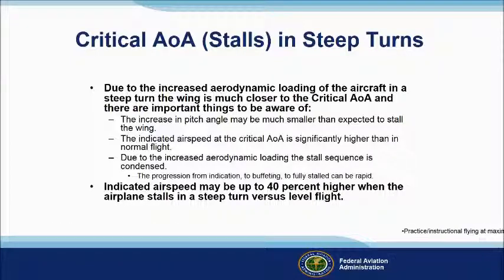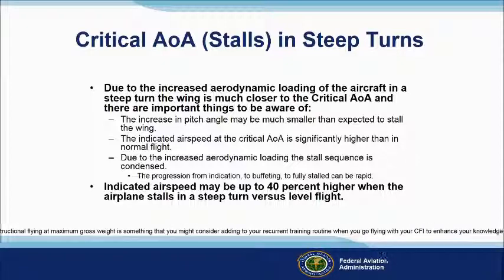Practice instructional flying at maximum gross weight is something that you might consider adding to your recurrent training routine when you go flying with your CFI to enhance your knowledge and ability, even in aircraft you fly on a regular basis. Pick 2 items like power on stalls and steep turns and fly short, back-to-back flights some afternoons so you can clearly experience the difference in the way your airplane responds.